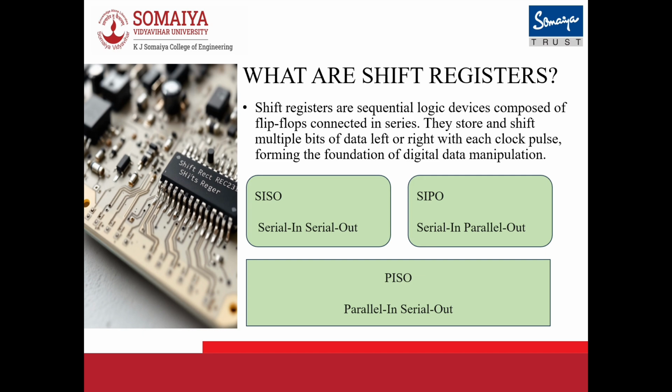Next is SIPO, serial in, parallel out. Data is entered serially, but we can access all bits together in parallel at the output. This is very common in display drivers where we load data bit by bit but display all outputs together.